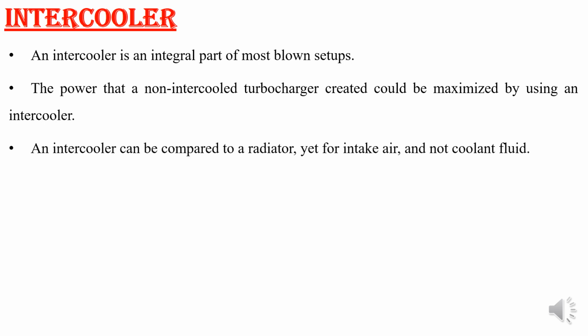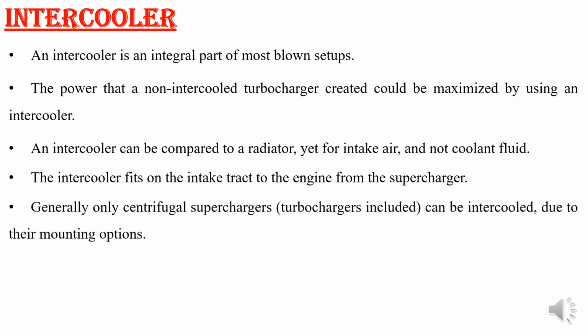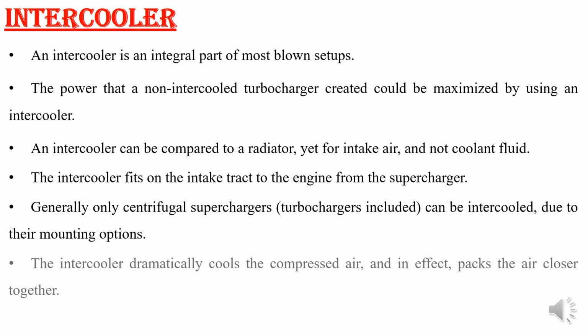An intercooler can be compared to a radiator type, because in a radiator, fins are there, which take the heat and bring the fluid back to the initial condition, and the intercooler is like a radiator type. So the intercooler fits on the intake tract, to the engine from the supercharger. Generally only a centrifugal supercharger can include an intercooler due to its mounting options. The intercooler dramatically cools the compressed air and in effect packs the air closer together.